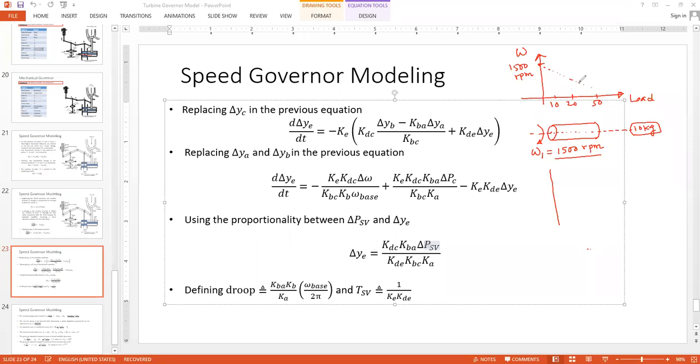It will be dropping until you change, let's say, the voltage input, or do something to control the speed to bring it back to its no load speed. For doing that, you have to change some parameter at the input side, control some of the parameters of the motor. But we are not doing anything. We are simply increasing the load at the shaft of the motor, and simply observing the speed deviation.